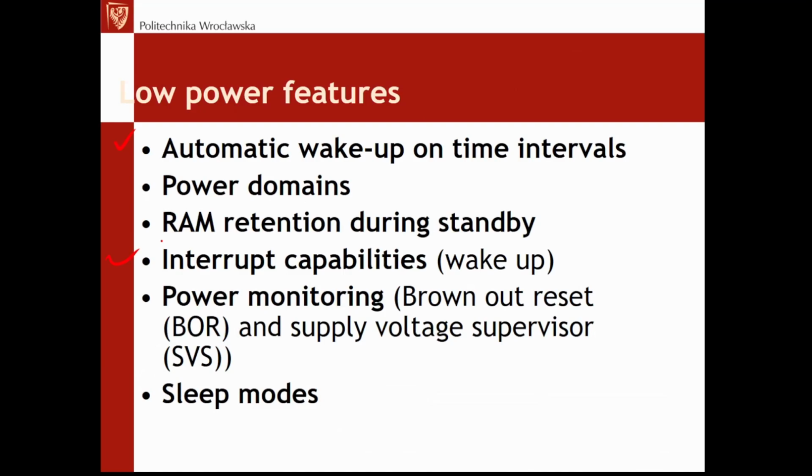So that we can put the microcontroller to sleep, and then it should be able to wake up automatically, either with the use of special timers, usually a watchdog timer or real-time clock, or through special external lines.